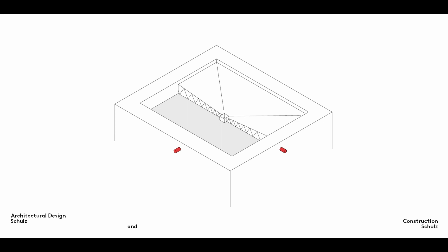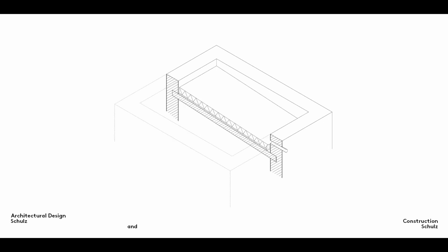As an alternative to tapered insulation, it's also possible to construct the entire roof surface with a slope. This removes the need for costly, bespoke tapered insulation, but means that the underside of the roof will also slope slightly and so alter the appearance of the room below. Imagine a large picture hanging on a wall in such a room. The line where the wall and ceiling meet would not be parallel to the top of the frame.